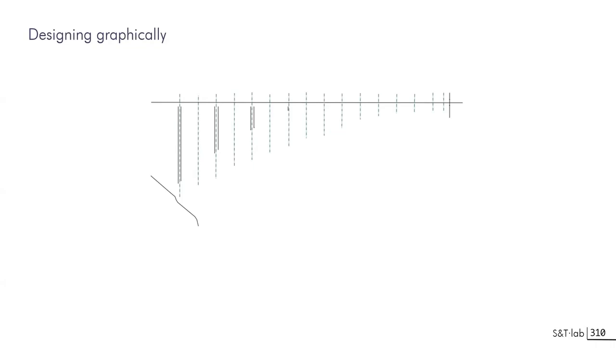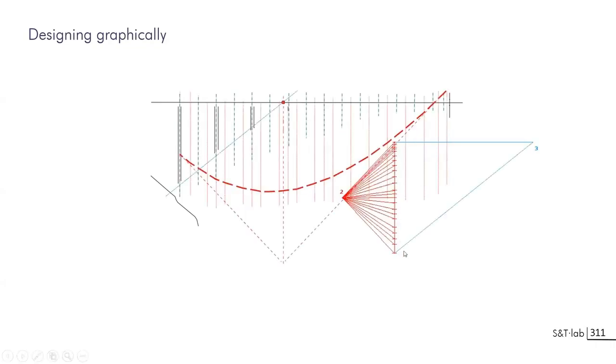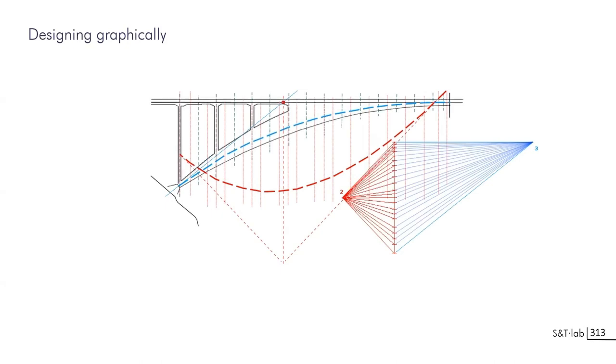You can take a first loading and you will be building the construction as you know. You get the pole and the direction from the support and start building this truss line. And once you have this truss line, you can balance the successive section of the arch and of the deck to correspond to the truss line. So that's the way this approach has been used in the very first step of this drawing from Maya.